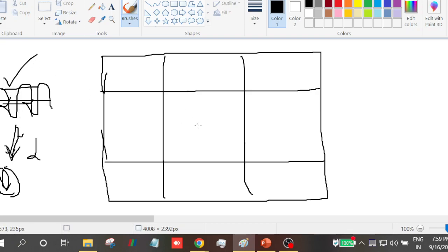Okay, so the way in which we do is that, see, this is our control volume, this square box or rectangle, whatever. So at the centroid we have a grid point. So there usually what we do is we store all the values of the variables: u, v, p. If three dimension, we take w also at this particular point only, at the centroid. That is in a collocated grid. But to avoid this pressure velocity decoupling, what we do is that we store only p here. This is the control volume for p now, the solid lines whichever are there.